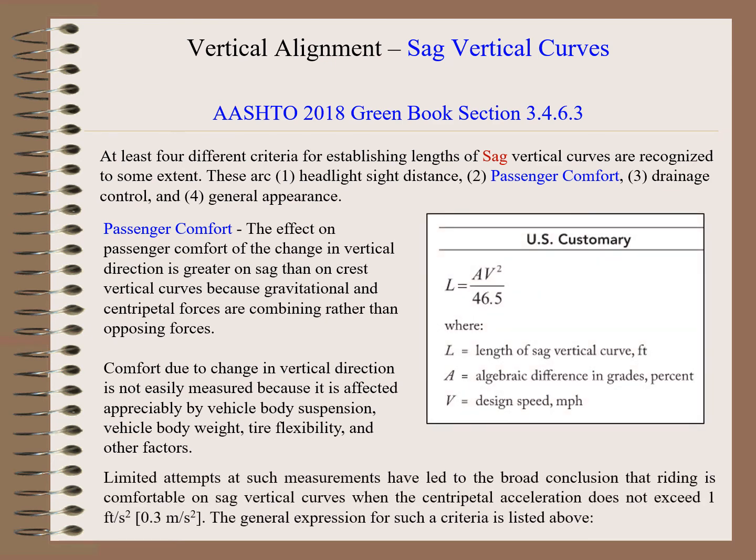Limited attempts at such measurements have led to a broad conclusion that the riding is comfortable on sag vertical curves when the centripetal acceleration does not exceed 1 foot per second squared. The general expression for such criteria is listed above.